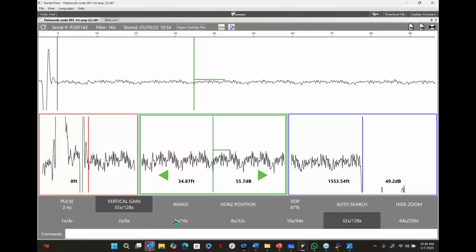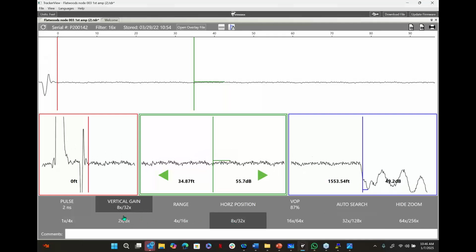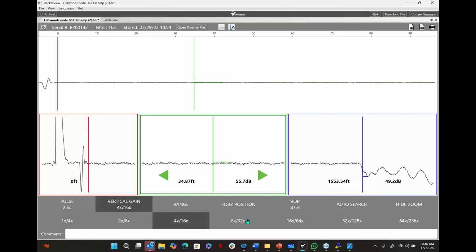First of all, I'm assuming this is aerial cable. And he says, it is. Okay, well, first things first, if you suspect that you have squirrel chews or cracks in your cable, the reason why it's so noisy is because the mere fact that you have an aerial cable, it's an antenna. If it's got cracks in the cable, it's just letting interference in.